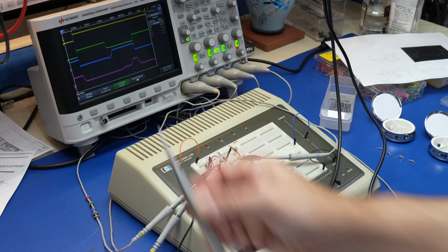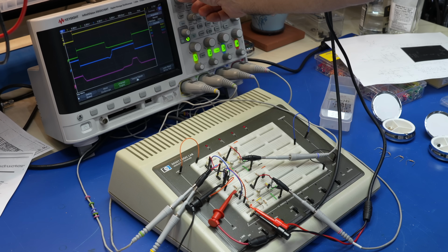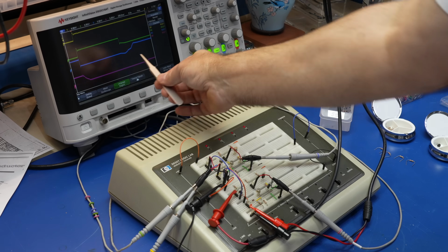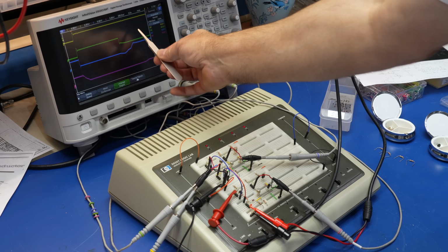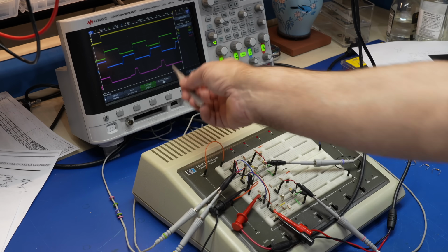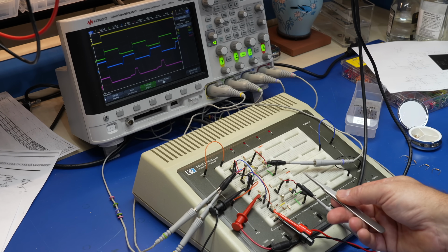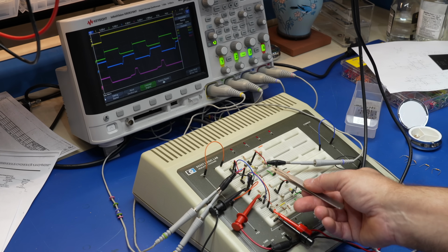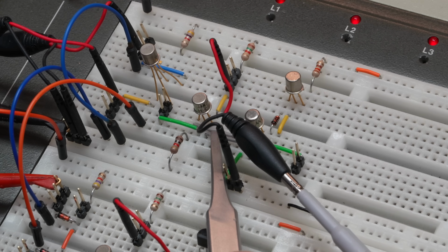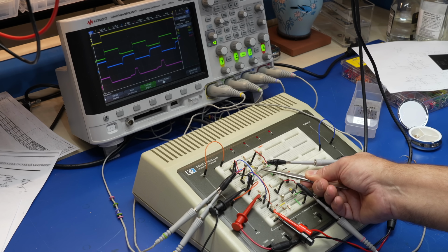But if you look closely at the TTL gate, the same effect is there too. See how it kind of does the same? It has a pedestal before it goes. So I was puzzled by this effect until I found out that I could get rid of it. I'm going to take this wire between Q2 and Q3.